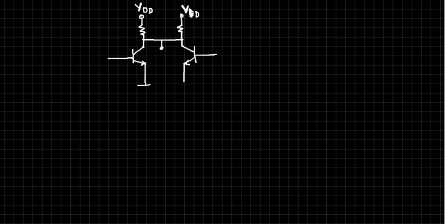Do you remember the transistor? We have seen that in the last semester. What if the input is high, what is the output? Suppose the input is growing, something like this. What is the output here, you tell me? What kind of configuration is this? Common emitter. Yes, it will be a 180-degree phase shift. So if it is logic 1, it will be 0 there, and if you give 0, it will be logic 1.